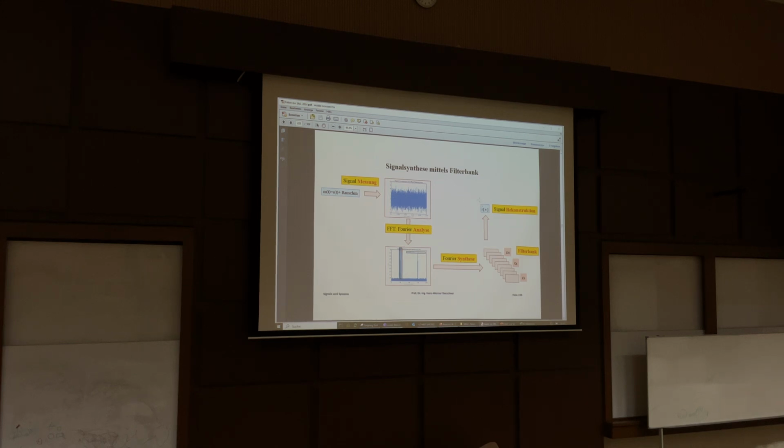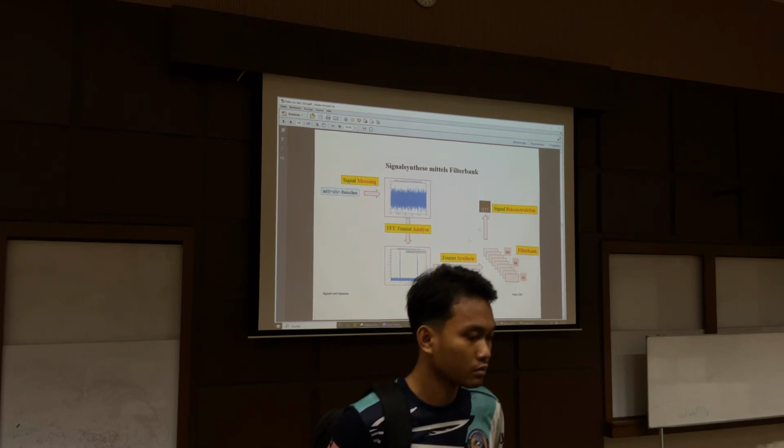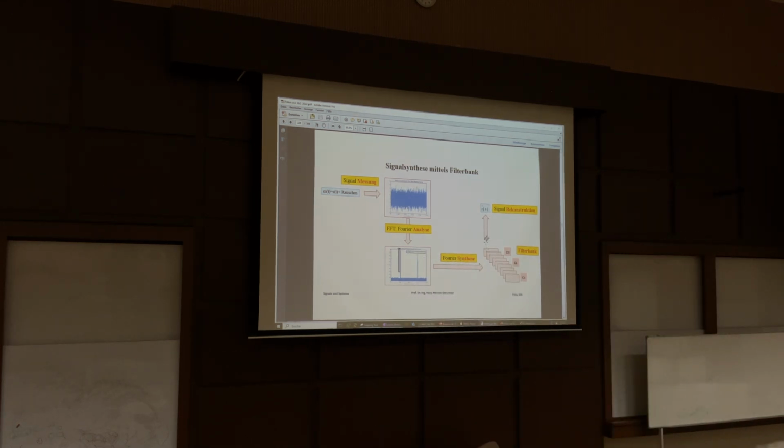And then I synthetically produce a signal, therefore we call that S with this roof on top, that is an estimation, a digital estimation, therefore S of n, discrete values, we will see that later in the day, of the real signal S of t. S of t is the real signal, and S of n is then the reproduced or the estimated signal because of our analysis and the reconstruction through these filter banks.